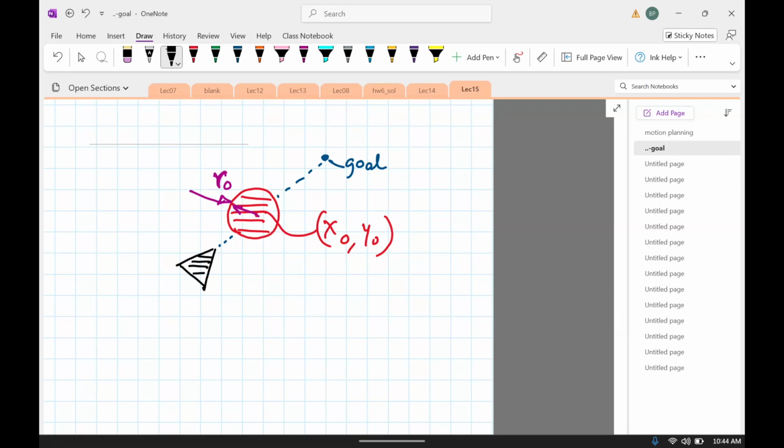So one way we can do it is we go towards the goal, but the moment we see that we are going to bump into the obstacle, maybe there's a distance sensor, maybe an infrared sensor which tells you the distance. So maybe we could say that we're going to do that a little bit ahead. We don't want to start turning the moment we hit the obstacle, right? So what we'll do is we'll create a buffer. Say this is a buffer. So the moment we're in this buffer zone, we want to start deciding turning.